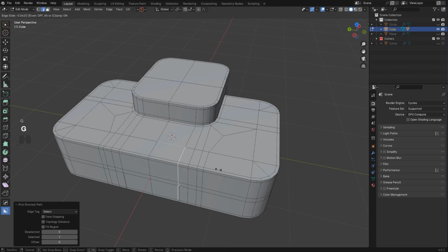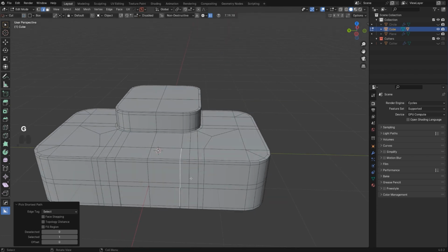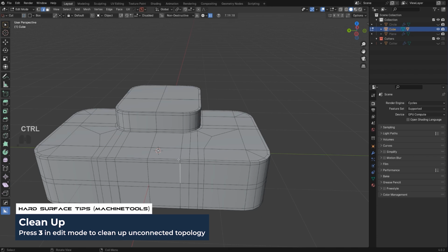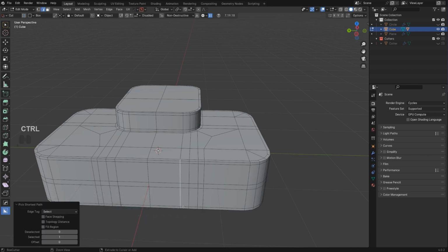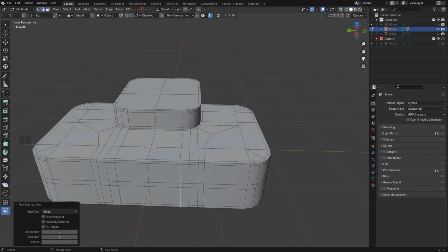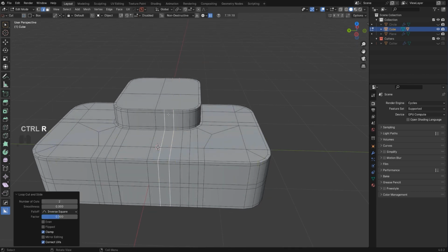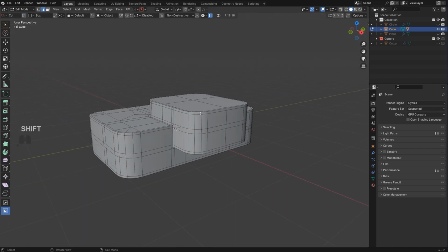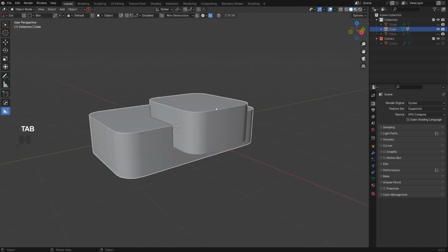Maybe you want to make things a little bit, let me just fix this here. Maybe you want to move things about to make them a bit more even, like for example, move this edge somewhere here to spread them about. Maybe you want to add more topology. It really depends on what you want to do, right? So this would be basically the Boolean to quad workflow.